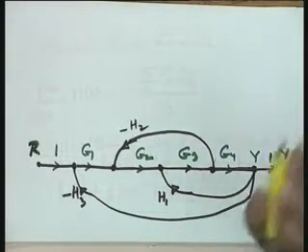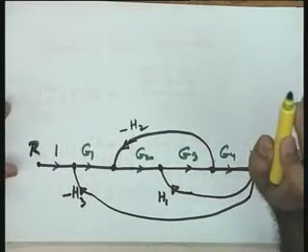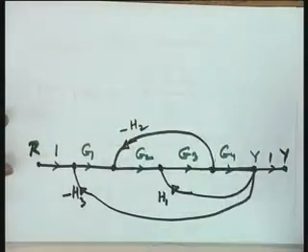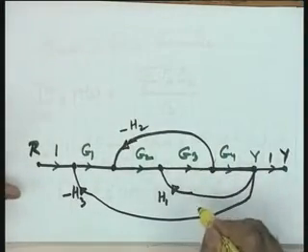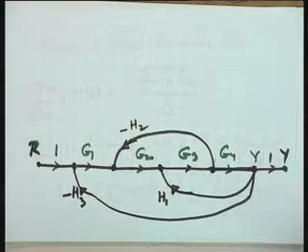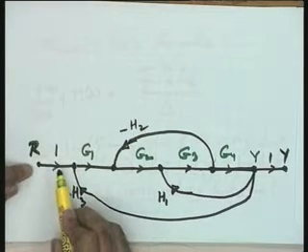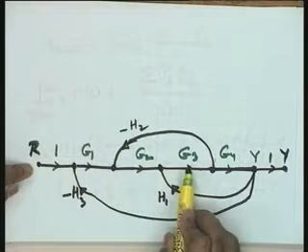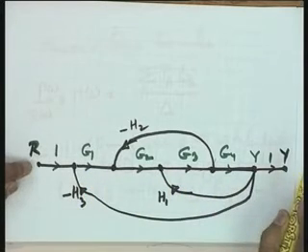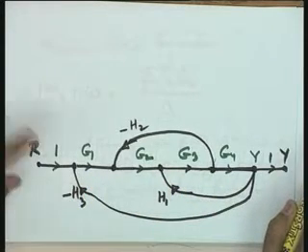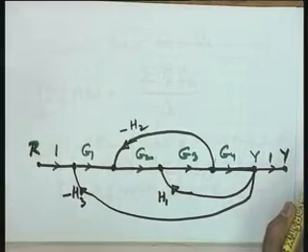So, Pk delta k, the k variable corresponds to the number of forward paths. The example before you is too simple, there is only one forward path. So, k is equal to 1 and P1 is 1 into G1 into G2 into G3 into G4, that is the gain of the first forward path. Now, let me go to delta k, the last term.